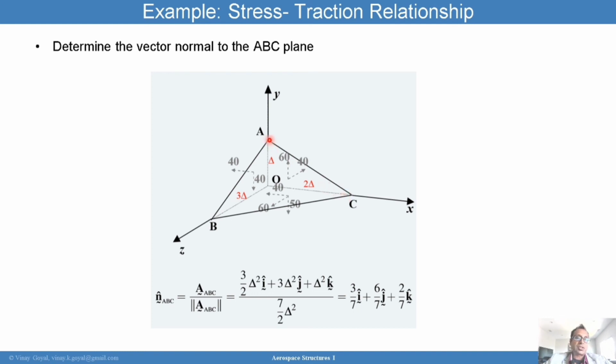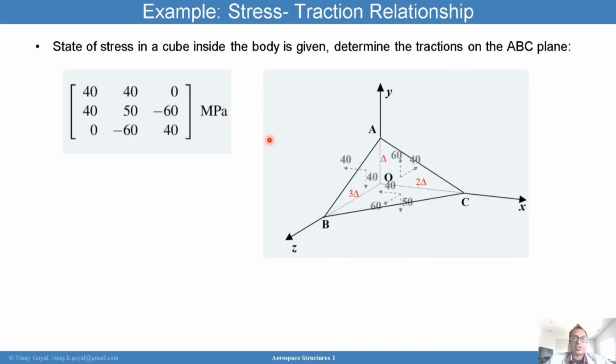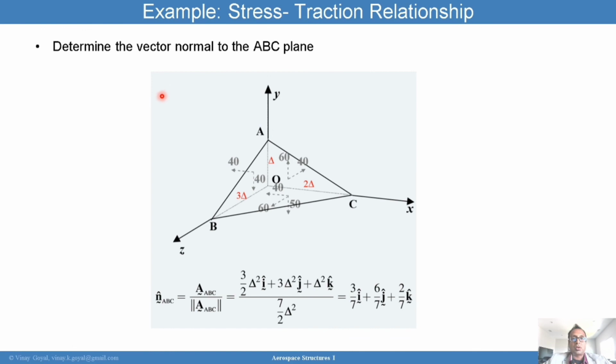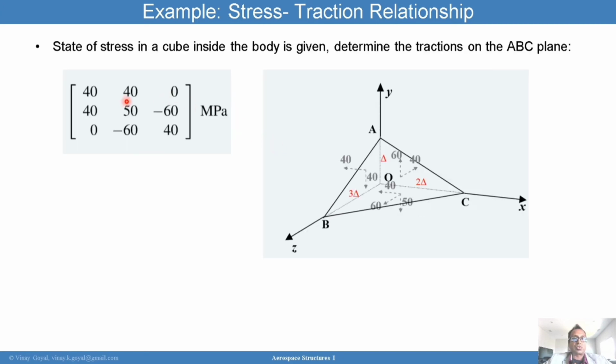Because what I'm really interested in is, given the stress components at a point, I want to know what the traction forces are on this face. That's really the question that we're after here. So I want to point out the importance of ensuring that you understand how the stress components are drawn in this cube, this partial cube, because we section that cube with a slice ABC. Normally this would be a cube. We sliced it with ABC, that plane.